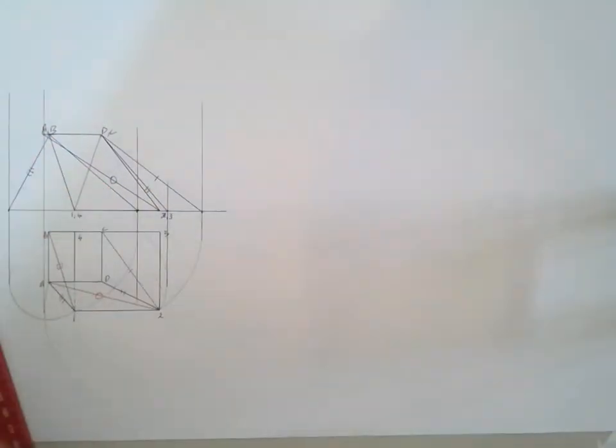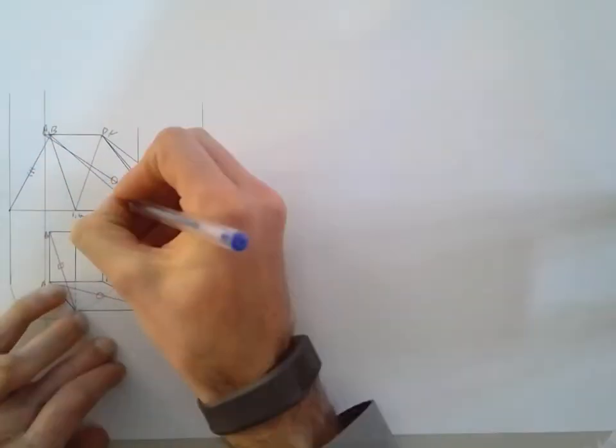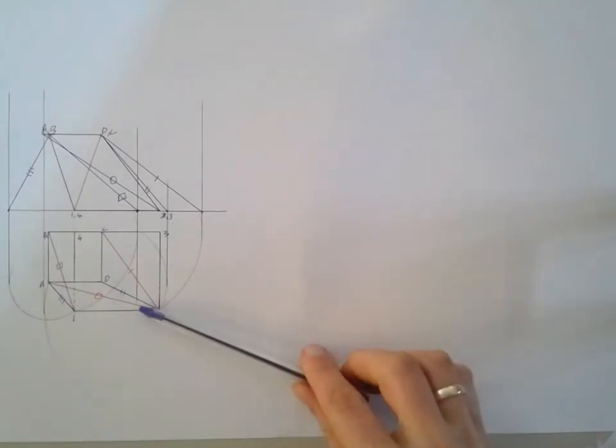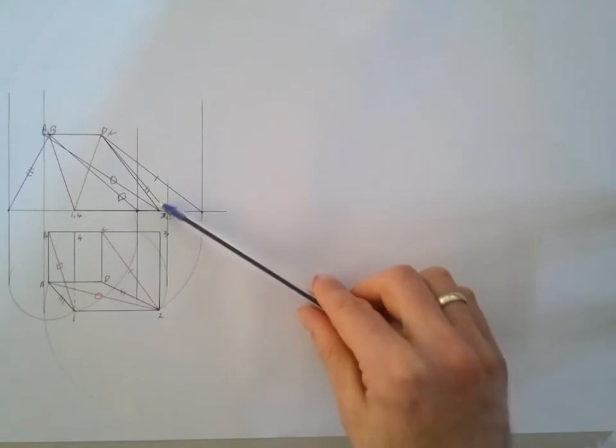And then I'm going to mark that true length of the square. Okay, now from that construction you can see obviously that if you don't go and mark the true lengths with either lines, squares or circles, you're going to get very, very confused between all of those lines when you have to go and complete the development. So make sure that you've labeled everything clearly, and make sure that you have used some sort of marking to have a reference between your top view and the true lengths that you found in your front view.